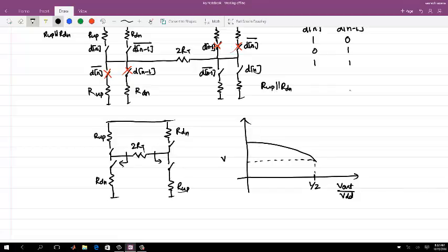So this is, sorry, this is I total from the supply, and this current is equal to VDD divided by 4RT, and this current was VDD divided by 2RT. This is what we have seen, right? In the previous case, when we fixed our Vout, we were always at the same point, right? When we just wanted a different output swing. But in this case, depending on the data pattern, we will be switching between a maximum and whatever in between the swing is.